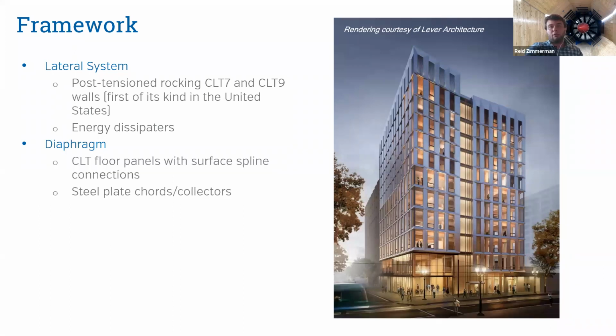Additionally, the diaphragm was going to be untopped. So it was going to be using the CLT as the diaphragm itself for resisting seismic forces, and, similar to what Jack has shown, steel plate chords and collectors. And again, it was not following a prescriptive path, instead following the alternate means and methods or performance-based design path.